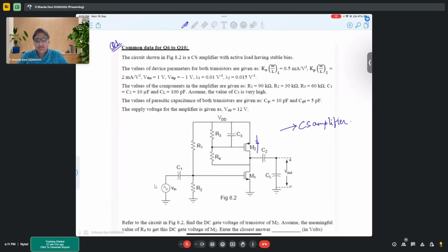in CMOS technology, we want all of our components to be made up of, first of all, MOSFETs, and secondly, the resistance that we can obtain from an active load. Here you observe an active load. Active load basically means active transistor. When you use a transistor as a load, we call it an active load. Here you are using a transistor to obtain the resistance.